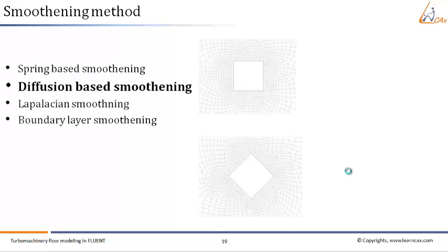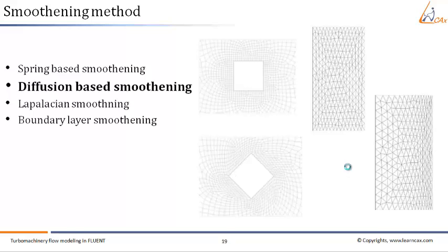If you want to specify spatially varying diffusion, you can control the diffusion coefficient by adjusting the diffusion parameter alpha. A value of 0 implies the diffusion coefficient is 1 and uniform diffusion of the boundary motion into the interior of the mesh happens. Higher values of alpha will cause the mesh closer to the boundary to move with the boundary, and the boundary deformation is felt farther away from the boundary. In the example shown, an initially uniform meshed square domain is deformed by moving the left boundary to the right.